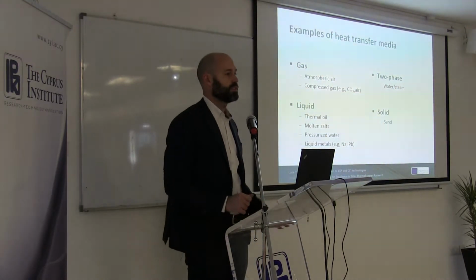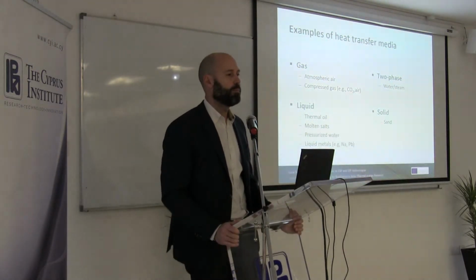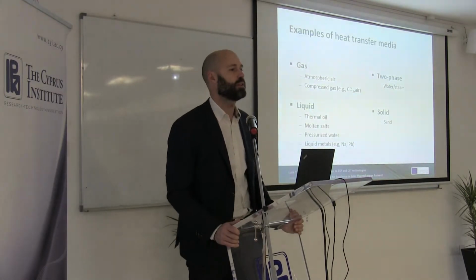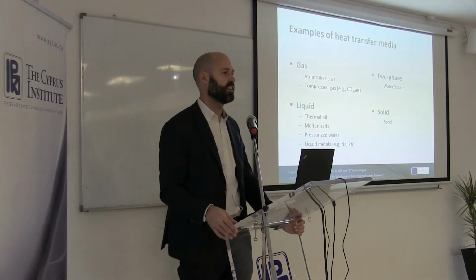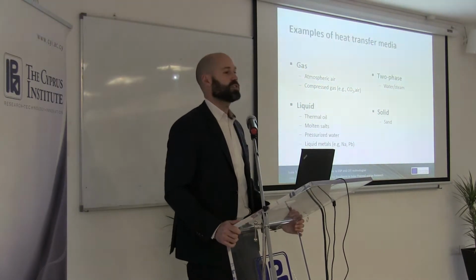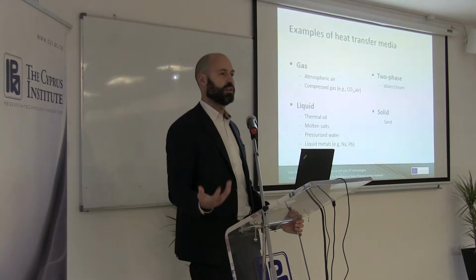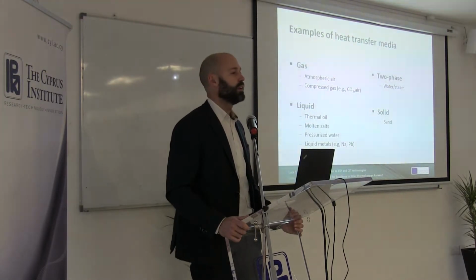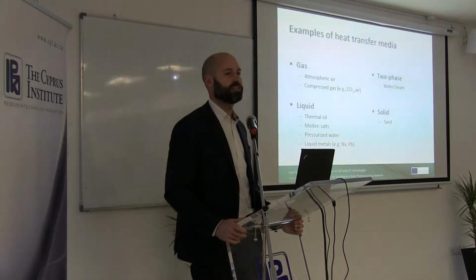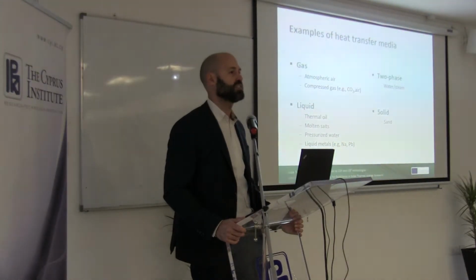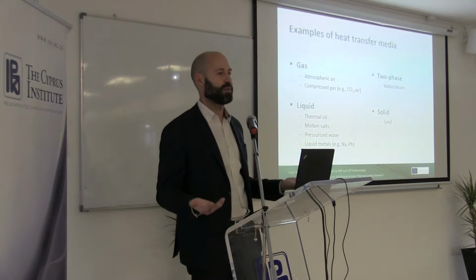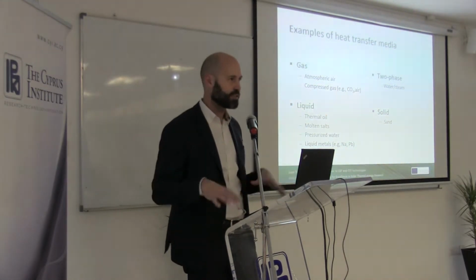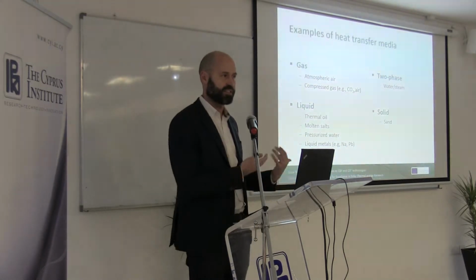Molten salt, this is a particular heat transfer fluid. It was developed within the nuclear industry, but it's now very, very important to the field of concentrated solar thermal energy. The most commonly used molten salt system is a mixture of potassium nitrate and sodium nitrate. It is stable up to slightly below 600 Celsius degrees, even if it's used up to 565 Celsius degrees. It is stable at ambient pressure. You don't need to pressurize your lines to keep this system liquid. This is the strong point. This is why we want to use this.